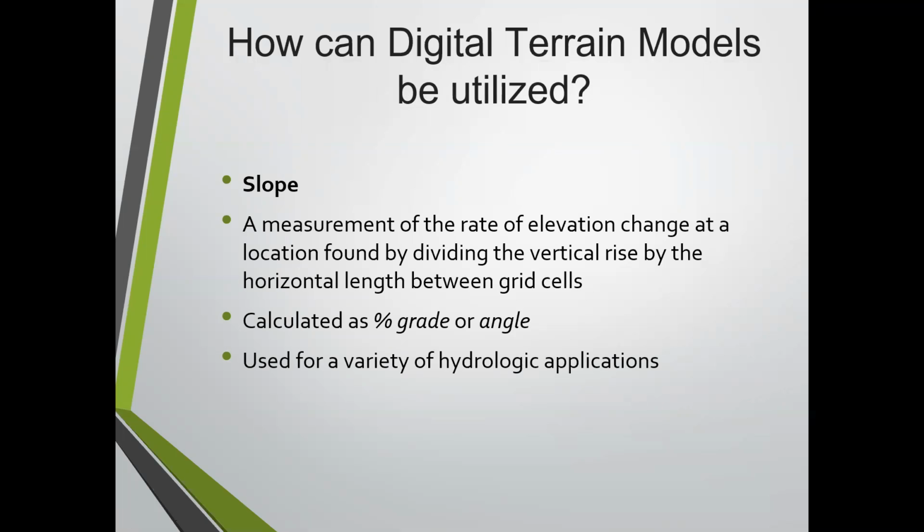It's also used in hydrologic applications, because the steeper it is, the faster your runoff is. So that determines your velocity, essentially your fluid flow. It also would allow you to look at accumulation of water in areas as well. We can see that as well, and extraction then of what we call watersheds.